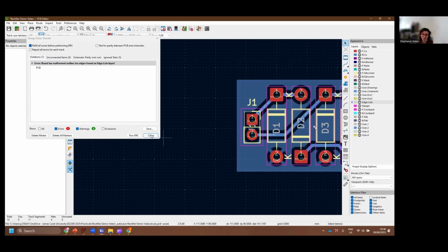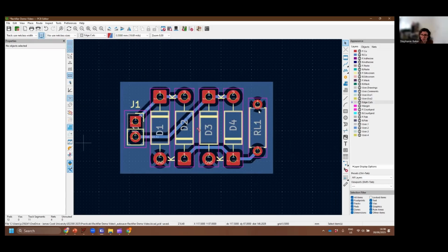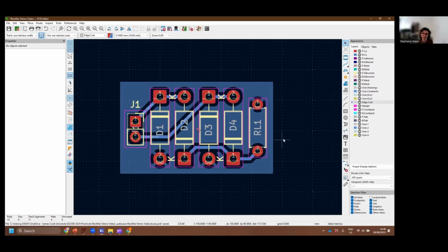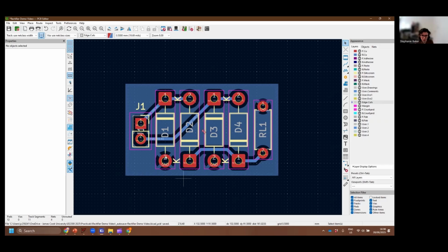I'm actually kind of surprised that the resistor was large enough. I'm just going to check that anyway. I guess I should probably believe it. Yeah, okay, it does have a fair bit of clearance. You could still make that pad a little bit bigger if you wanted to make your soldering job a little bit easier. So you could bump that up to, for example, 1.8 and 1.8. You can actually select multiple and change them both at the same time if they're the same type. So if it's a round one, you can change them all together. If they're square, you can change them all together. All right, so let's do that. That looks pretty good. I'm pretty happy with that.